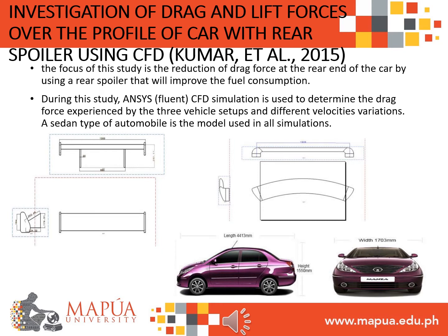Investigation of drag and lift forces over the profile of car with rear spoiler using computational fluid dynamics. The focus of this study is the reduction of drag force at the rear end of the car by using a rear spoiler that will improve the fuel consumption. During this study, ANSYS computational fluid dynamic simulation is used to determine the drag force experienced by the three vehicle setups and different velocity variations. A sedan type of automobile is the model used in all simulations. The figure shown from left to right shows the rear spoiler dimensions from the first setup, the rear spoiler dimensions from the second setup, and the generic car model dimensions.